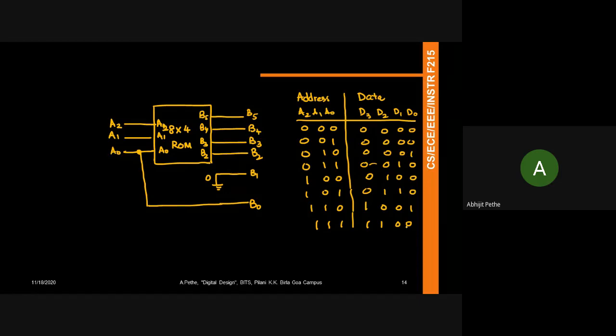In reality, there will be a pin known as an erase pin. Once you give a 0 there, essentially you can erase the entire ROM, but we don't worry about that in this class. In this class, we'll assume that the ROM cannot be written. So you write the ROM once with this. Once you're done with that, it becomes a combinatorial circuit, and then you can use it to generate the square of a 3-bit number at any time.